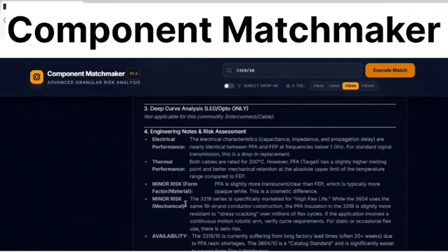The minor risk in terms of mechanical is that this is specifically marked for high flex life, while the 3604 uses the same 19 strand conductor construction. The PFA insulation in the 3319 is slightly more resistant to stress cracking over millions of flex cycles. If the application involves continuous motion, such as robotic arms, verify the cycle requirement. For static or occasional flex use, there is zero risk.